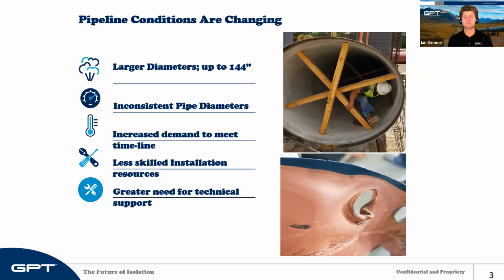And with this, we've seen significantly more segmented type gaskets, which I'll get into more later, but that's when the gasket OD meets a certain diameter. Sometimes the gasket has to be joined from multiple sheets in these larger diameters. And we've been producing these for a long time, but they provide challenges. And it's a pipeline change that we see issues with as they go.